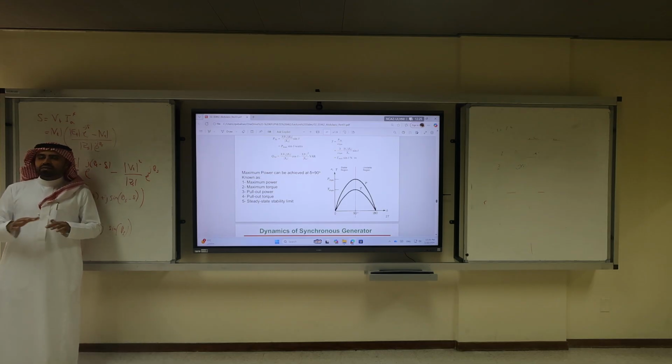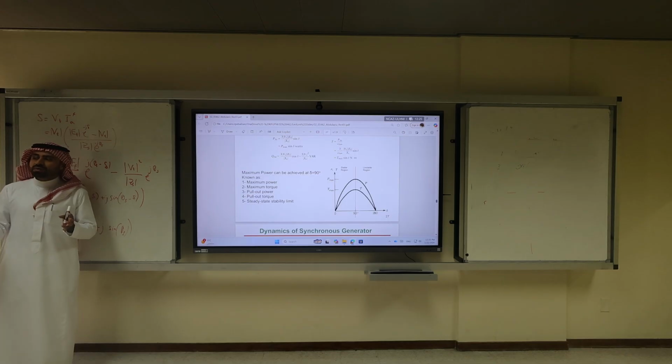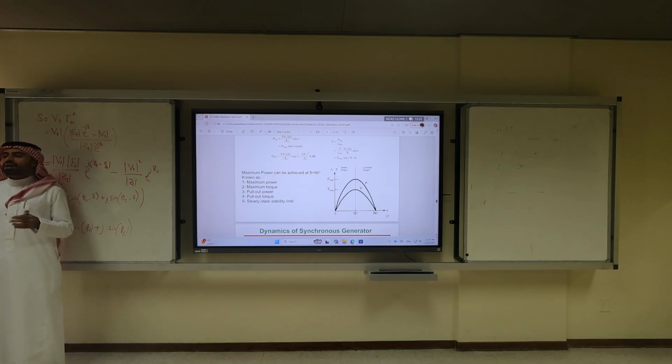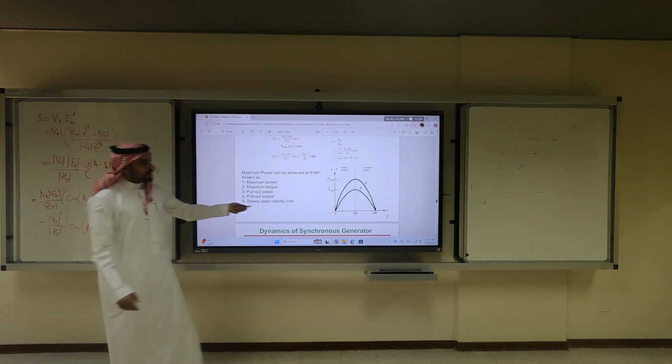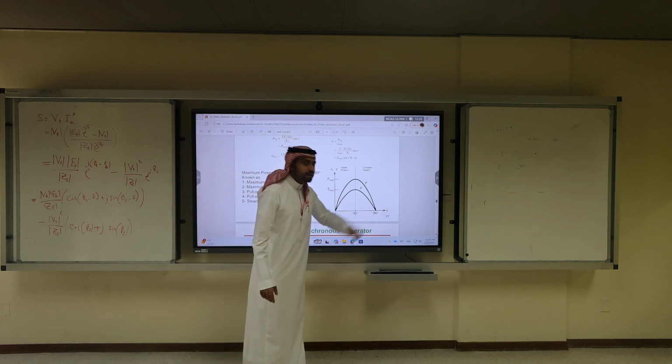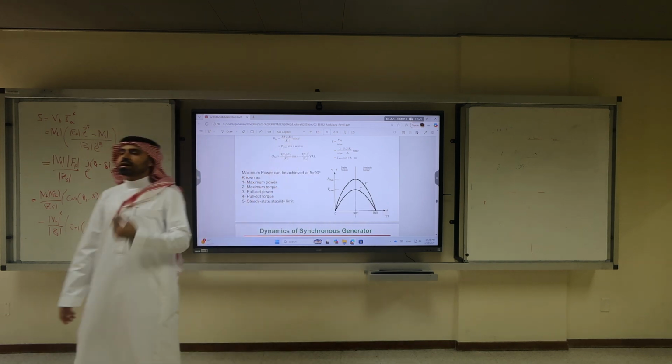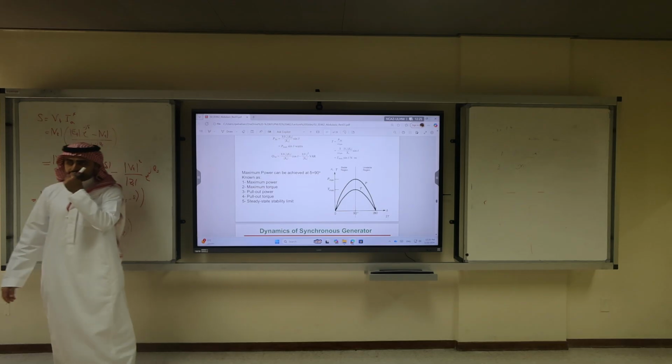The rotor magnetic flux is constant, uniform, but because it's rotating, it becomes a uniform rotating magnetic field. The magnetic flux in the stator is by nature AC, so it's by nature rotating. So if you rotate a constant magnetic field in an already rotating magnetic field, you have to make sure that delta alignment is there, and delta clearly impacts how much power. If you think about it, yes?